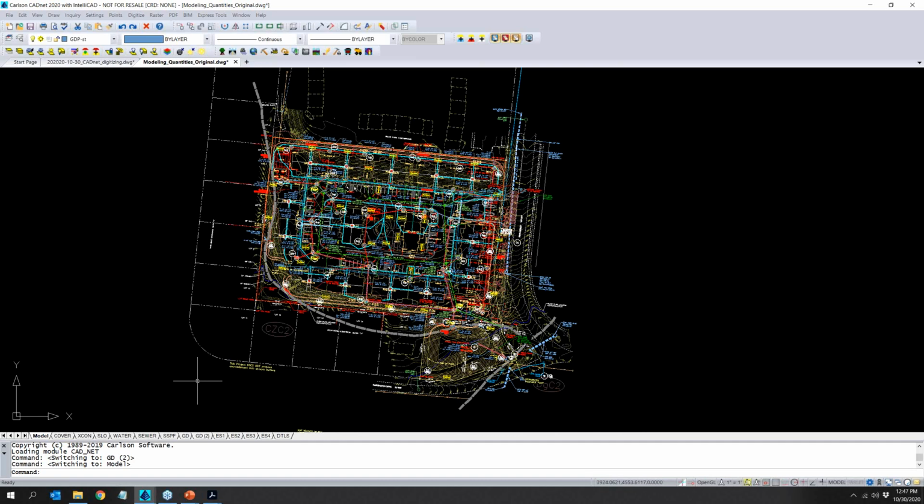So I've jumped ships here a little bit. So let me just make sure that you understand. So if you are doing this for estimating and takeoff purposes, you're going to end up most likely with some cleanup that needs to be done in your drawing. And you're going to end up with some elevating that needs to be done. You're going to have 2D entities that to get accurate surface models, to stake by or to get quantities from, you're going to need to elevate that stuff.